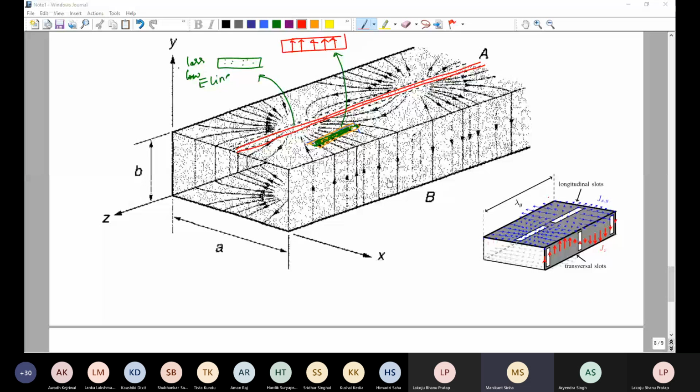So the waveguide dimension was 0.4 times 0.9 inches. You can just Google the dimensions for the WR90 waveguide. And sir has also explained that in this frequency range, it supports a single mode of operation. The WR90 waveguide supports a single mode of operation in the X band. So this we forgot to explain.